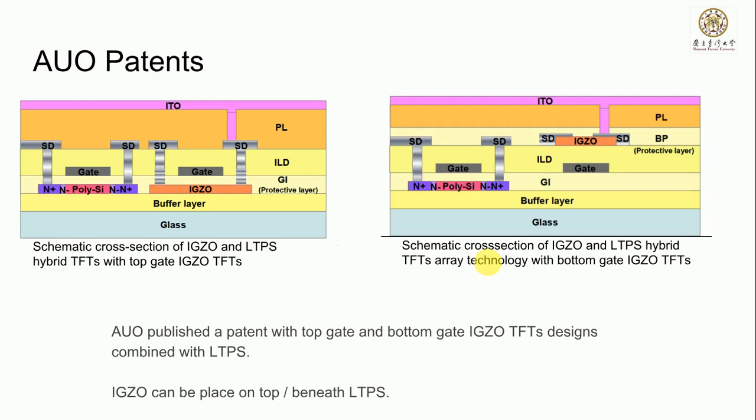Apart from Apple, there are actually many more companies also working on LTPO. And here's a patent file from AUO, one of the big companies in Taiwan. They explore different ways to place the IGZO driving circuits in the design. On the left side is the driving circuit with a chop gate IGZO design, and on the right part is the IGZO TFT placed on the bottom part as the driving gate. Each design has its own advantages.